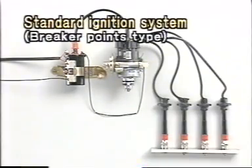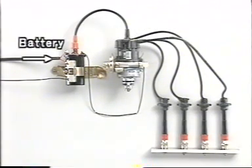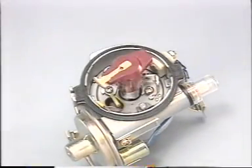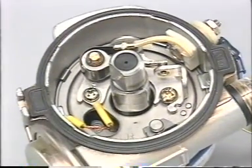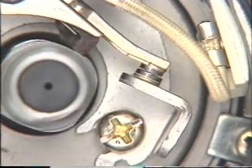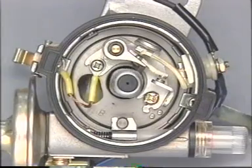Let's have a look at a standard ignition system. Unlike a transistorized ignition system, a standard ignition system turns the primary current of the ignition coil on and off mechanically using the distributor's breaker points. The rotation of the cam on the distributor shaft opens and closes the breaker points. This turns the primary current of the ignition coil on and off.